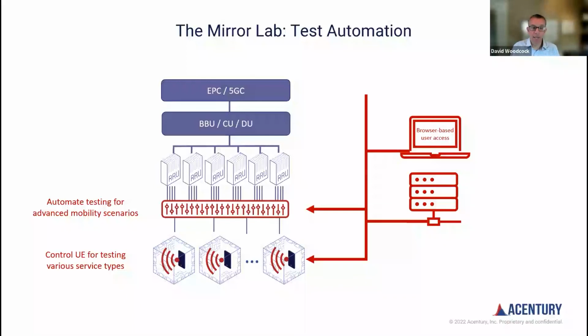Changing which signals are combined together duplicates carrier aggregation and MIMO, and changing the attenuation of the signal paths mimics handover between sites. Because the switch matrix is under software control, it can manipulate many RF signal paths independently all at the same time. Trying to perform a 4x4 MIMO test with 3 carrier aggregation using manually controlled rotary attenuators would be next to impossible. It's almost certainly not possible to do it exactly the same way twice.